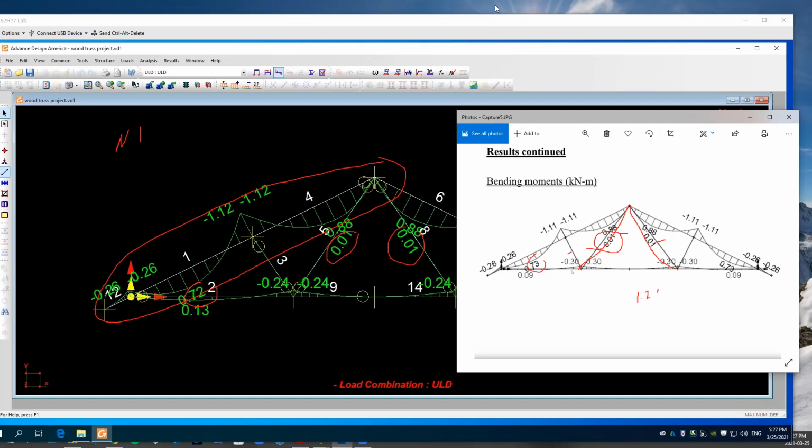in a real truss with the fabricators of these trusses, okay. The only reason I told you to use a 2x4 here is because you only have 2x4s in your tables. You understand? That's why I asked you. But in reality, in a real truss, these would be made with 2x3s. You understand? And they would be sufficiently strong. The web members are usually made with 2x3s, and they're sufficiently strong to take care of those axial forces. You understand? But since there's no 2x3s in the tables that I give you, and even in the handbook, I tell you to use a 2x4.